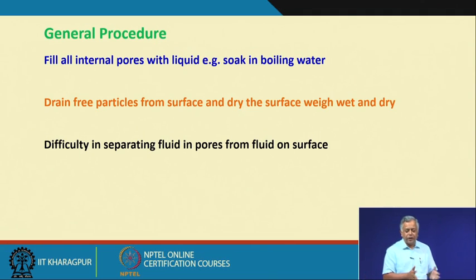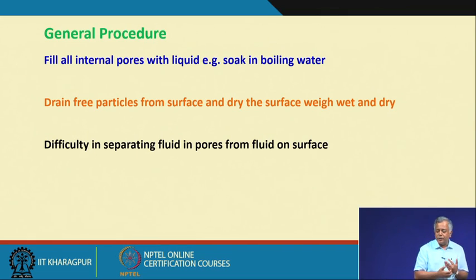So, you know the internal pore volume, but the problem is the water can only get inside if the pore is an open pore. What I am trying to say is that if I have a pore inside a big particle which is not at all exposed on the surface, how will the water get inside? So, there is a chance of having an erroneous result.